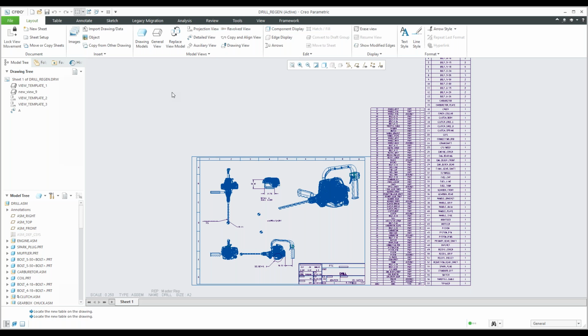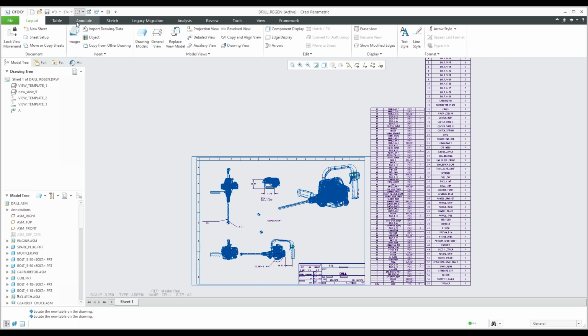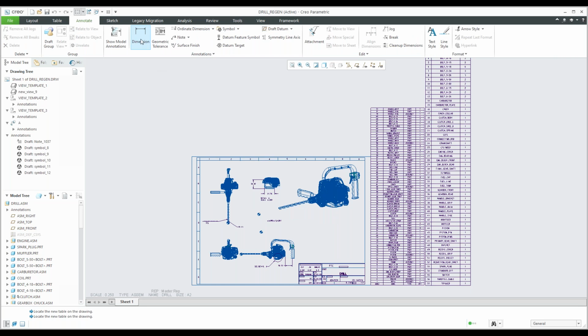If you do a lot in the setup and the planning, then the creation will be a lot easier. When you get into the creation, your first step is to lay things out, add models, and create your views if you don't use a template. Then start with the annotation, dimensions, and symbols, which can make your life a lot easier. So that's what I wanted to show.